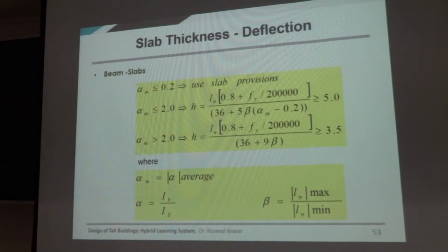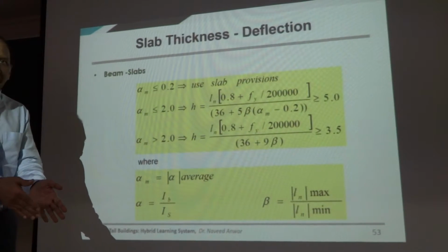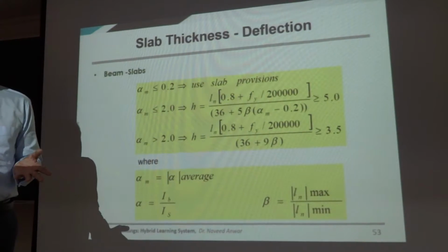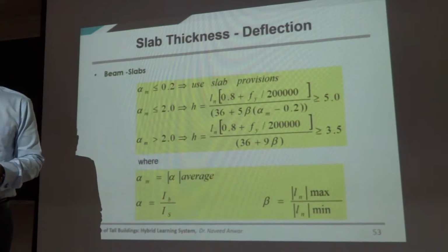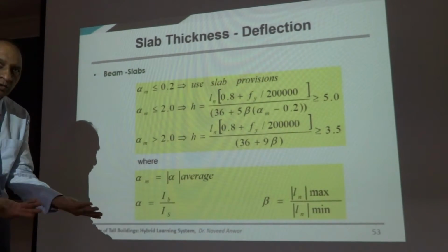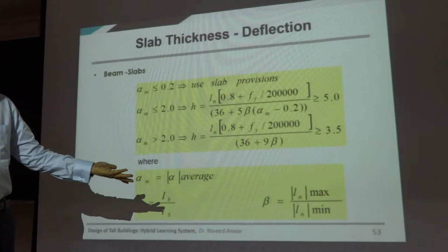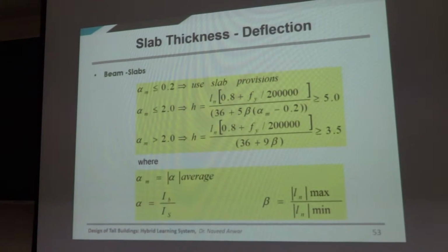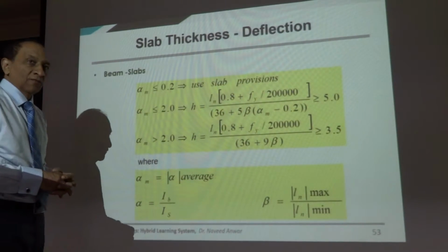profile. A slab has different deflection along the column, and next to the column. So there is no single system that you can use. Very difficult, because the strip itself is deforming this way, and it's also deforming the other way. So at the center line, deflection will be different, a little bit here, different, and so on. So very, very hard to calculate the deflections of the flat slab system.